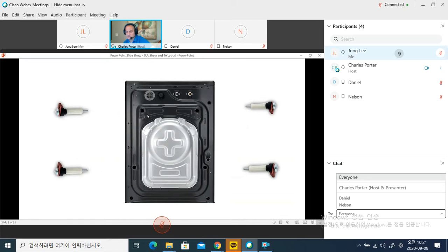And sometimes installers, or if customers install them themselves, they completely miss this and they don't pull them out. So they do need to be removed. If they don't remove it and the customer uses it, it's definitely going to cause really bad vibrating and shaking. If they use it long enough, it likely will damage the inside of the unit as well. So if you find these shipping bolts inside there,